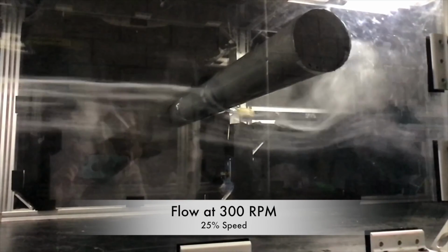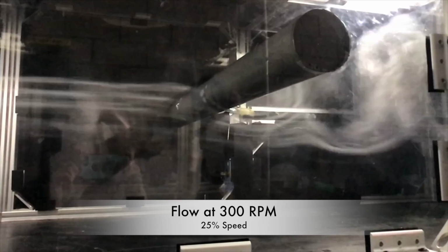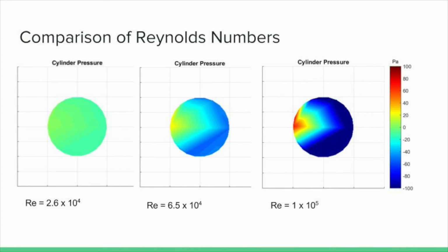The frequency of the shedding at this value is 24 Hz. Again, it has increased because the Reynolds number increased. Comparing all of the clean cylinder pressure graphs to each other, it can be seen that all portrayed similar pressure characteristics, with a high pressure at the leading face and a lower pressure at the trailing face. However, it can be seen that as the Reynolds number increases, this difference becomes larger and more prominent.